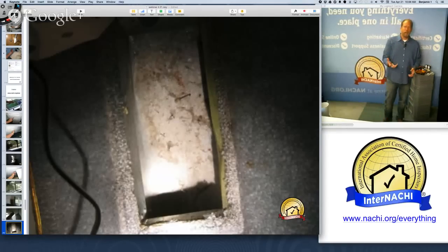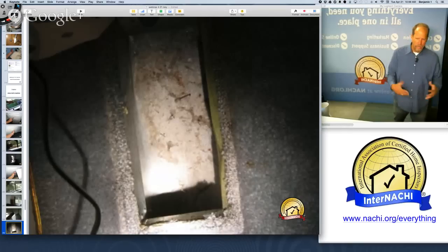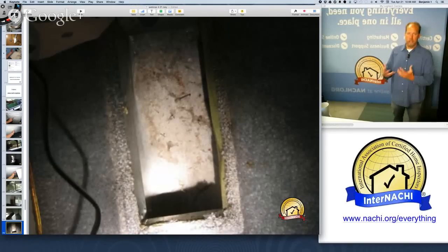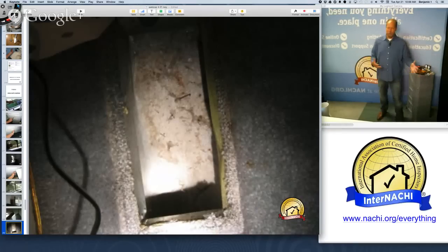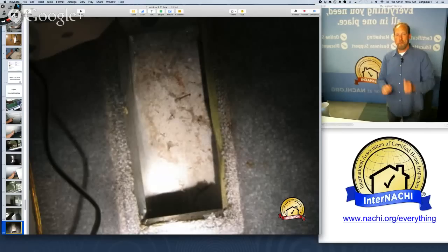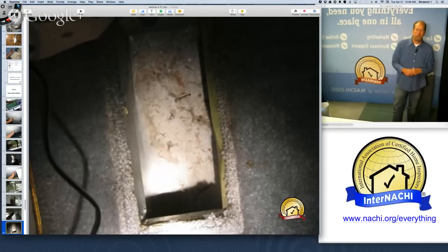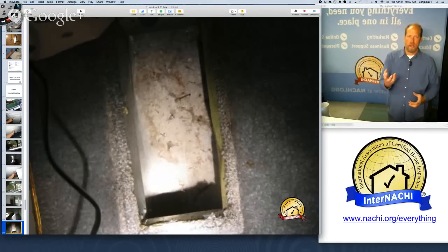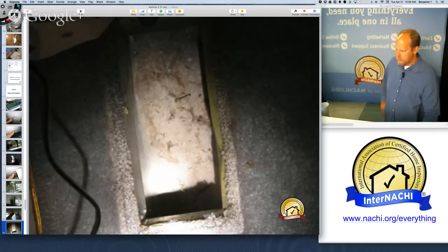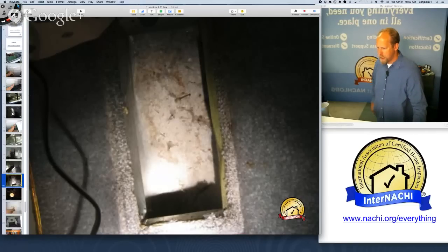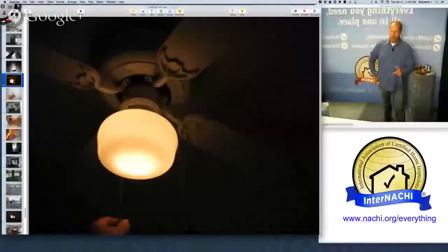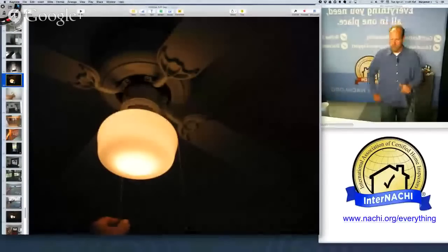And a lot of indoor air quality issues come from lack of maintaining the duct system. And usually ducts are filled with stuff, even from the very beginning of the home's life, when the builder had the contractors just broom sawdust and nails into the ductwork, right? So sometimes I find big piles of sawdust and nails and chips in the ductwork. Well, that could be a very valuable piece of information. It may not be negotiated upon prior to closing, but something that the homeowner, your client, can do after they move in, get the ducts cleaned.